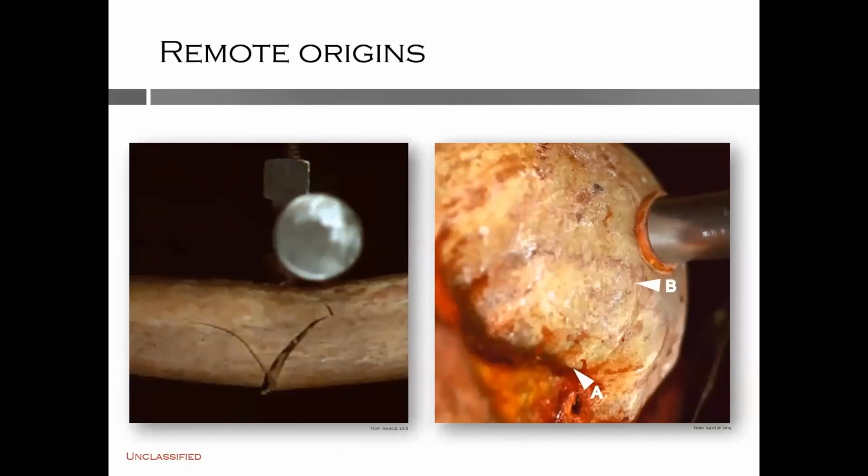Pictured left, a femur broken in bending has a fracture origin on the side of the bone opposite the impacting object, since bending forces impose tensile stresses on the opposite side. This image also shows that the fracture origin is not directly opposite the impact site, indicating the location of a localized weak point in the bone in the zone of tension.